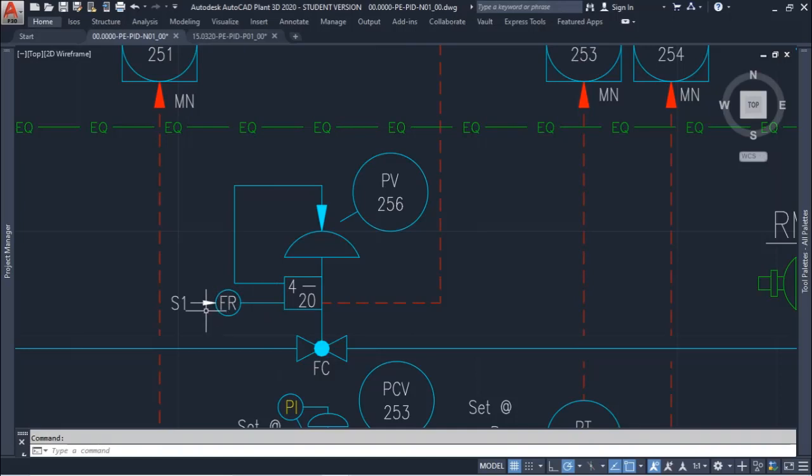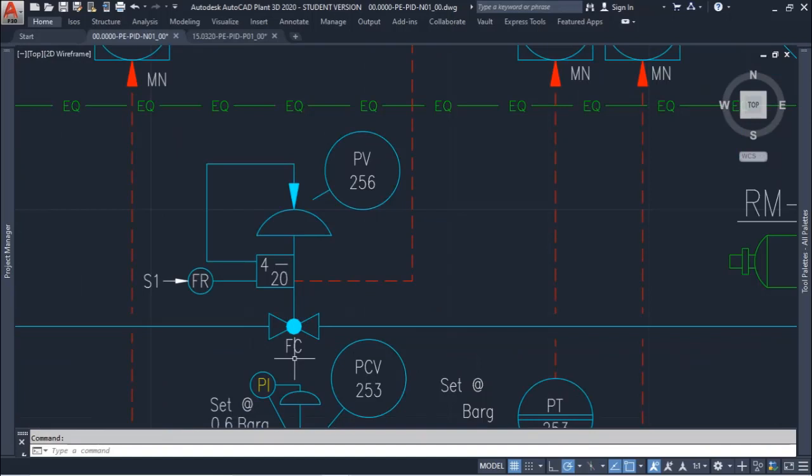So it means that the instrument air is at a pressure higher than is allowable for the control valve actuator, and because of that we need a filter regulator. And here we have also the information of the fail-safe position of the valve. In this case we have fail close. So if the instrument air fails, or if the instrument air is closed, this valve will automatically or mechanically close, because it needs instrument air to operate.